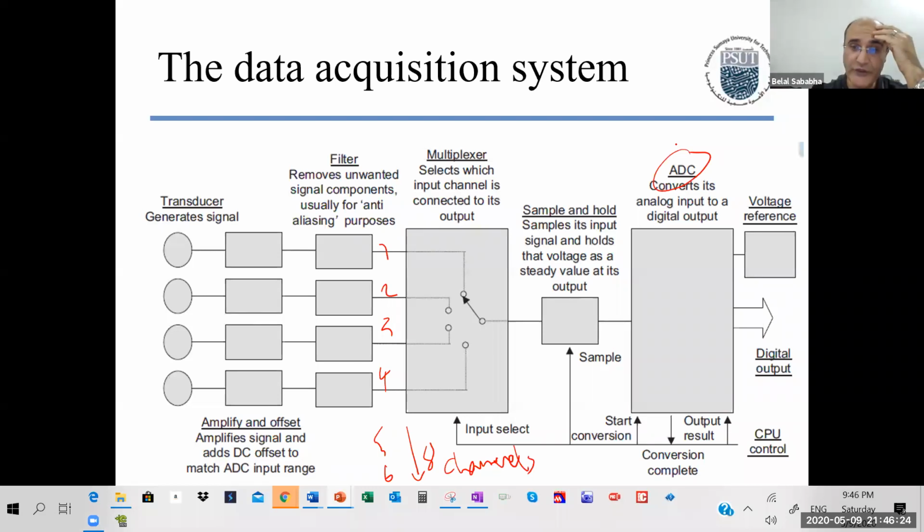We cannot afford to have 8 analog to digital converters. We only have 1. There's a multiplexer here that selects what channel, what sensor you want to read. I want to read the sensor connected to AN0 on port A0, the one on port A2, the one on port A3. You select here. We have the control to select, to save ADCs.